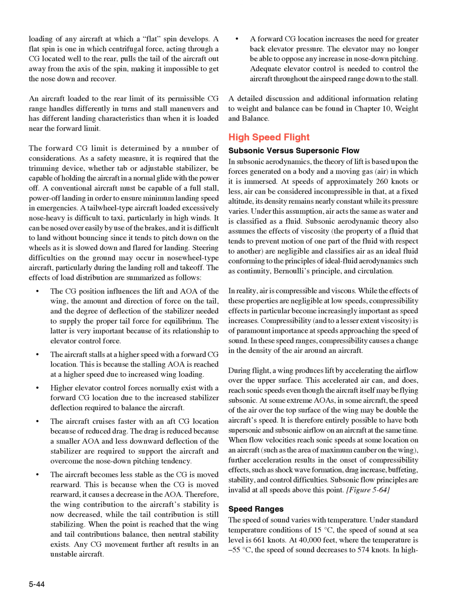When flow velocities reach sonic speeds at some location on an aircraft, such as the area of maximum camber on the wing, further acceleration results in the onset of compressibility effects, such as shock wave formation, drag increase, buffeting, and stability and control difficulties. Subsonic flow principles are invalid at all speeds above this point. Figure 5-64, speed ranges. The speed of sound varies with temperature. Under standard temperature conditions of 15 degrees Celsius, the speed of sound at sea level is 661 knots. At 40,000 feet, where the temperature is minus 55 degrees Celsius, the speed of sound decreases to 574 knots.